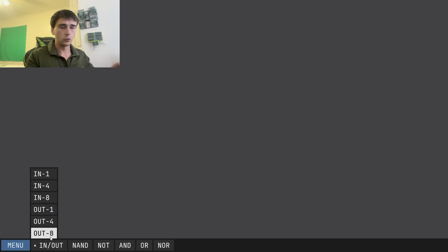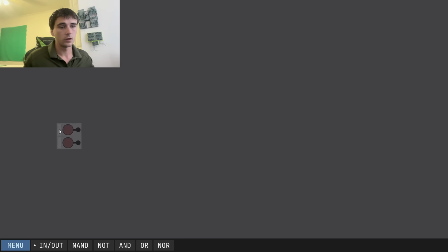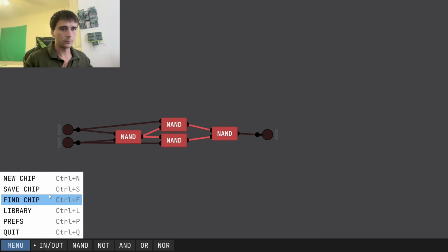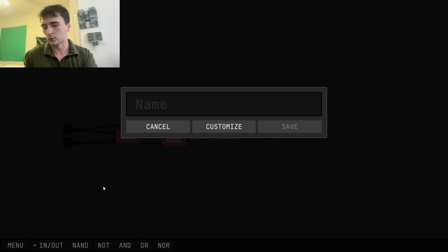And then now we got to go into these two different gates called the XOR gate, which is what the name Fool's Or is named after. So if we take 4 NANDs and go into this configuration right here, we get a special type of gate. And now the output is on if either of the inputs are on, but not if both. If both of the inputs are on, the output is off. And there's multiple ways to make this gate, but this is the way that I remember how to make it, and it's called an XOR gate.